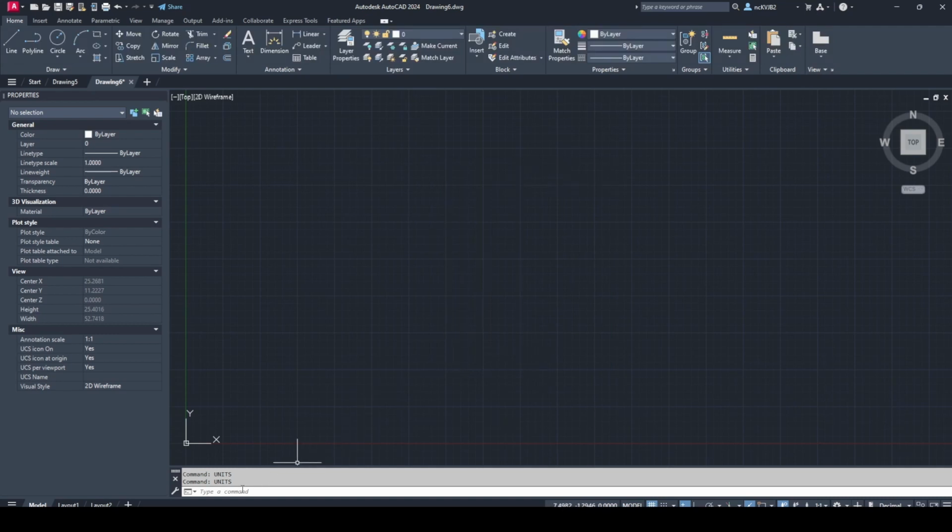I mentioned the command line before. If you have had no experience with AutoCAD before, you are probably wondering what that is. The command line is probably the single most important tool you can use to make the most of AutoCAD. The command line allows you to type commands in and operate the functions of AutoCAD without having to click buttons or go through menus. At any point, unless you are within another operation, you can start typing and it will be entered onto the command line.